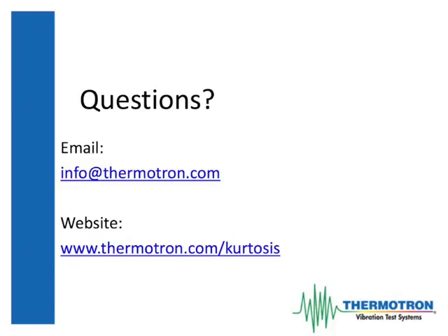If you've taken analytical mechanics in college, that's sort of how you'd think about it. At any given instant, the product is effectively in a Gaussian vibration state with a quasi-static, or nearly constant, GRMS level. And as long as you get the same distribution of power levels, it doesn't matter from a fatigue standpoint how you got there. You could do it by window multiplication, amplitude modulation, level schedules, although that's a bit crass maybe.